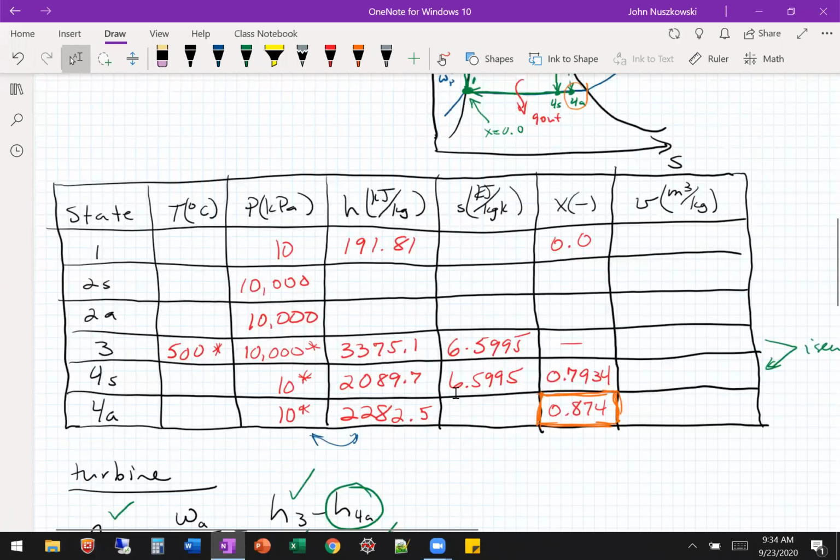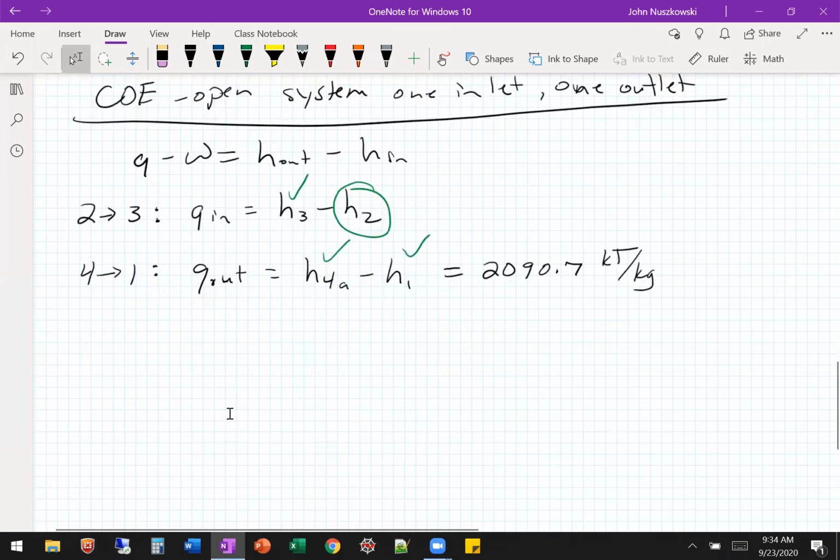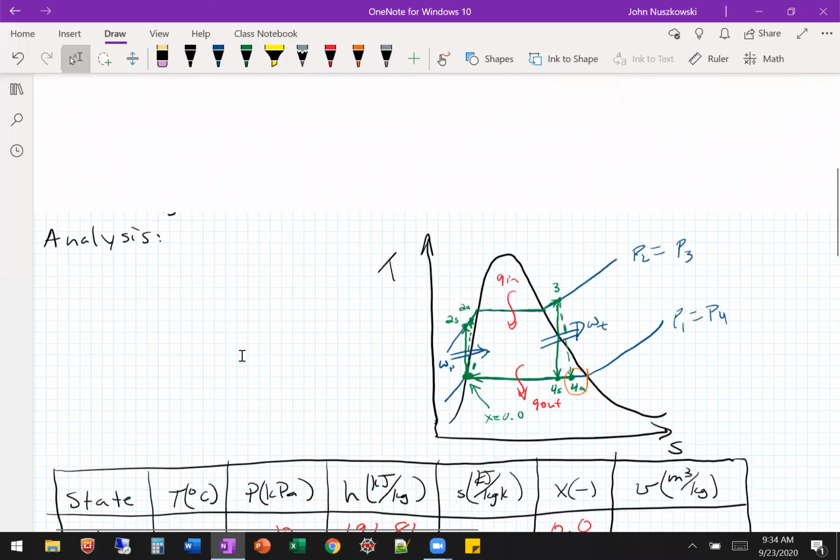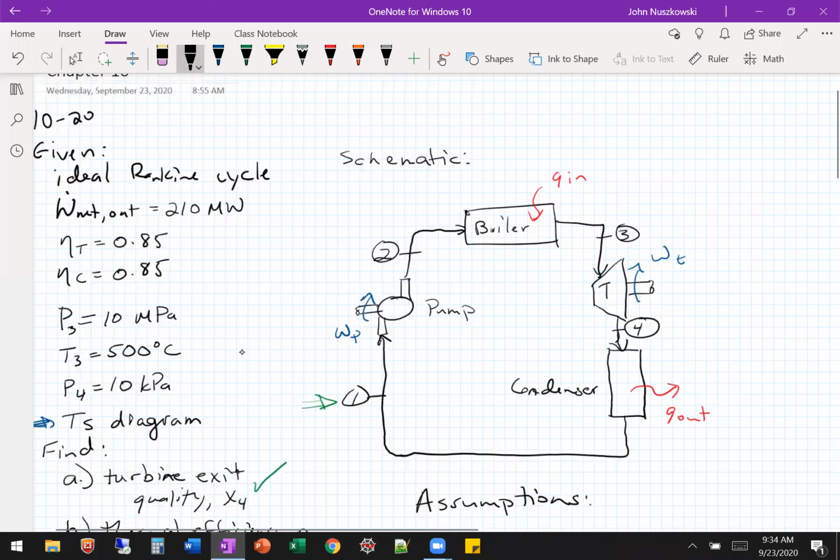All right, so then we need to figure out our enthalpy at state 2. We need to figure out information for state 2 actual. Would we do the same as we found for this? So using the pump efficiency. Yeah, so we'll have to use that pump. I put P at the top when I said givens, so the givens should be pump.